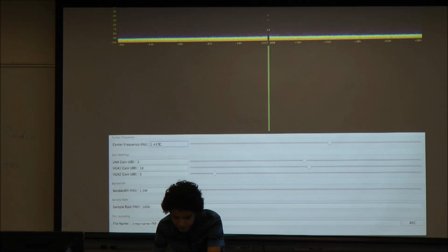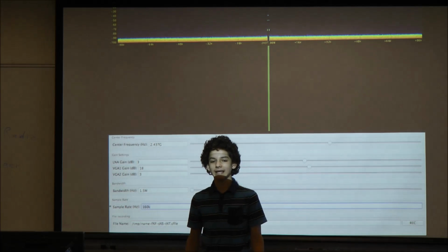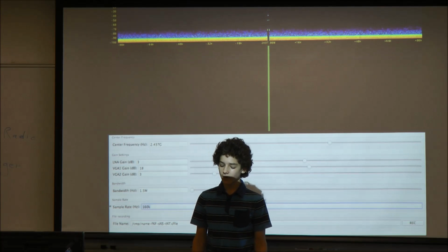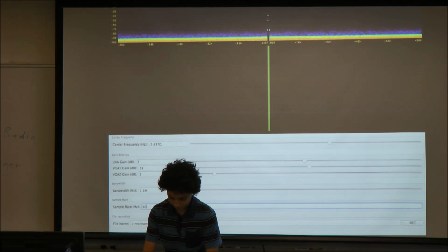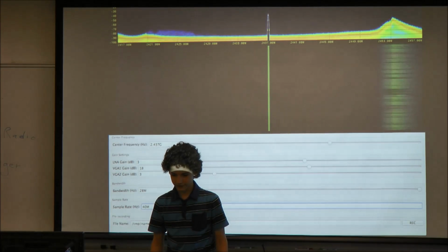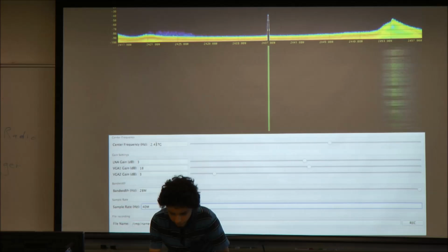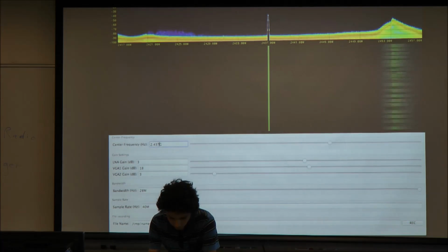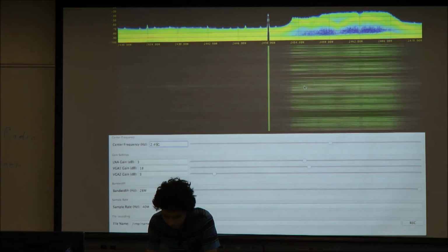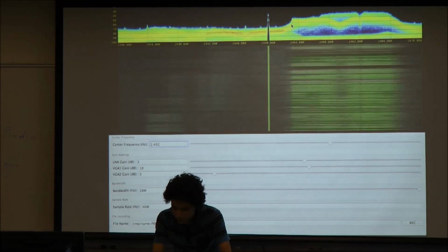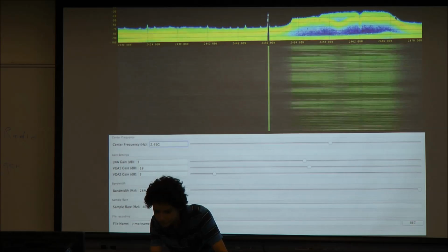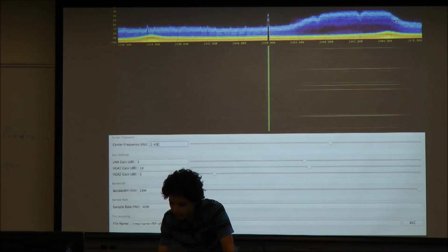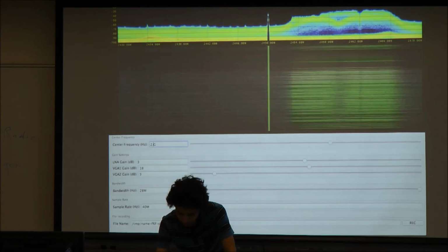Oh no, this is using the sample rate. So it defaults to 160 kilosamples per second. So it's a really slow sample rate. I'll just do 40 megasamples per second, and now we're seeing stuff. So if we tune up a little to say 2.45 gigahertz, we see this, and it goes from about 2.454 to 2.46 or so. So that's probably a Wi-Fi thing.